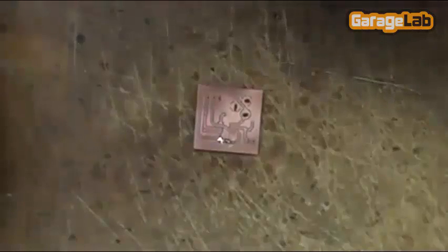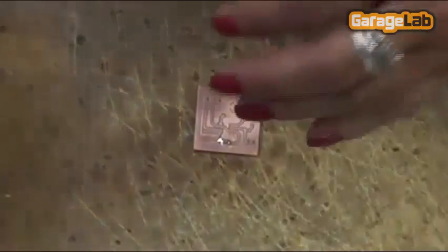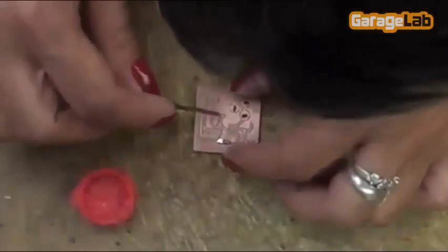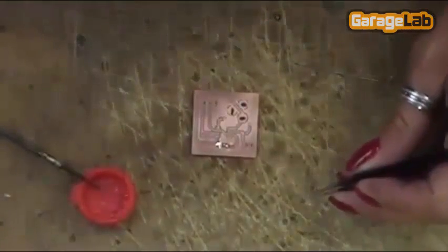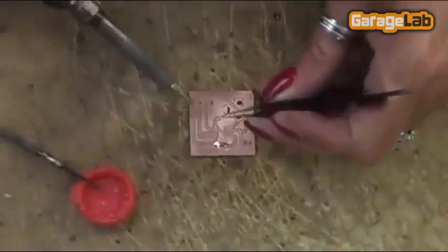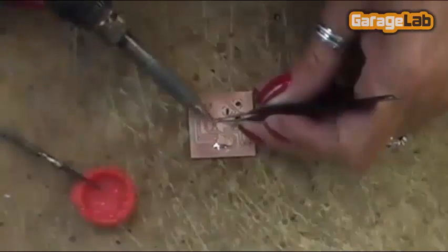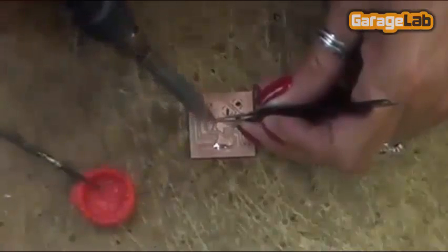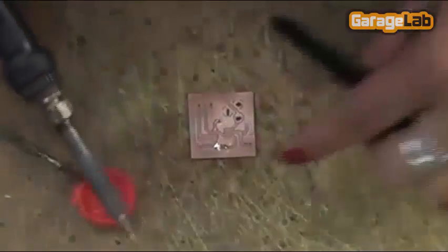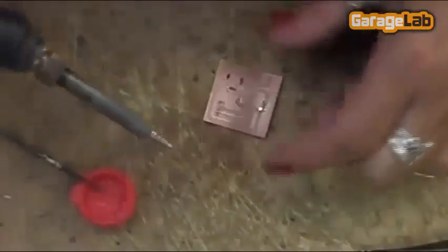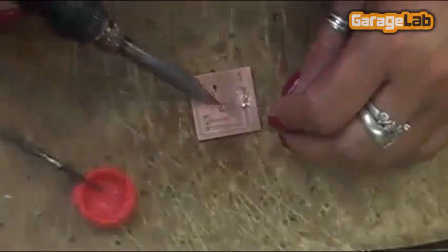Finally, it's time to solder the components. As we are working with SMD components, you have to use flux in order to provide a good condition to solder the SMD component. Pass the flux over the surface you are going to place the component. Then, with the help of precision tweezers, place the component. Now put very little tin over the iron soldering tip, just enough to fix the component, as you can see on the screen. With the component in the right position, it's easy to solder, as you may be used to.